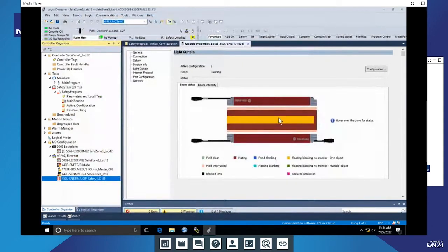One product group might have a specific size, and the other a different size. So I'll explain it to you over here, right? For this example, I'm going to get Jack to place his hand just in the light curtain, and now you can see only part of the light, the black lenses of the light curtain, is blocked. Now, say for instance, the next situation, we have a higher type of pallet going through, which means we'll have twice the length going through.